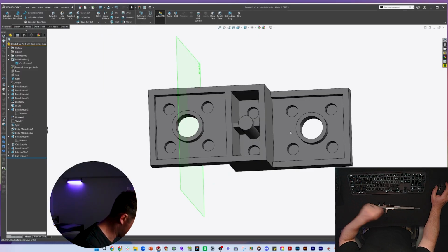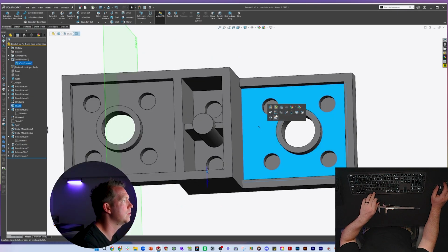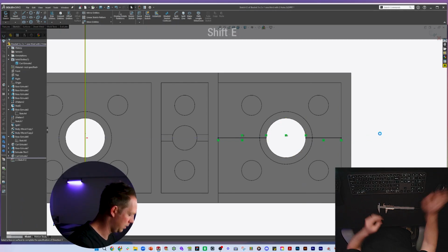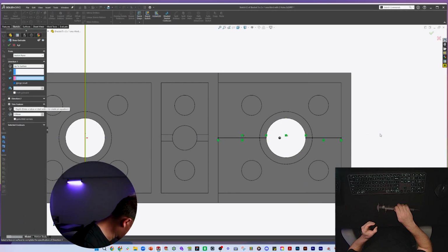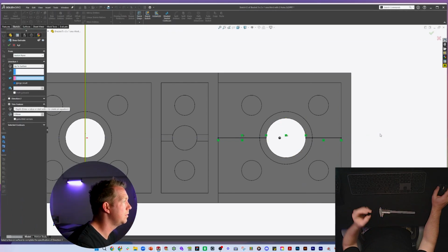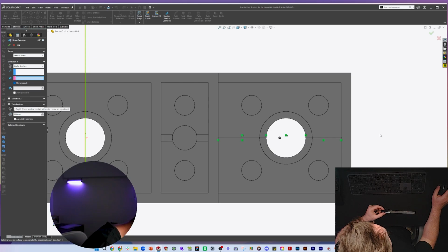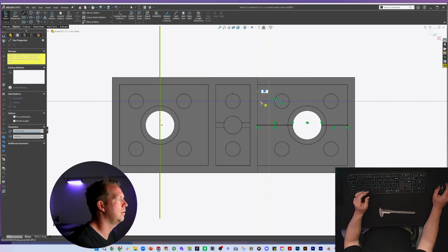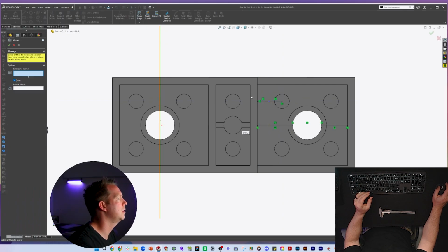We need to do these ribs first. So there is a rib that goes through the middle of this. We will go from that face, and from that face, we're going to go to a thickness of 1.1. While we're doing it, we'll do these other ones, which are in line with these holes. So more, got another one here, and I can mirror this about this.